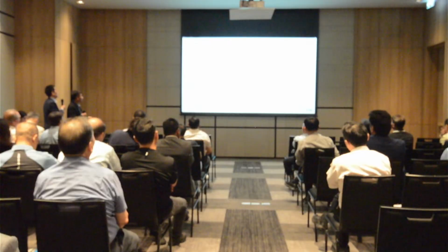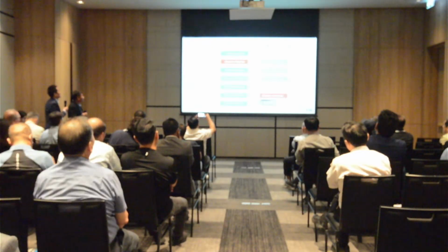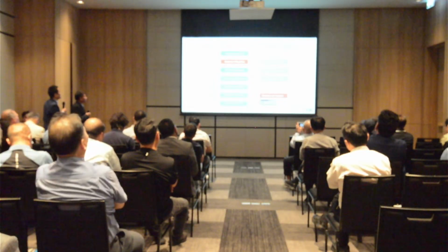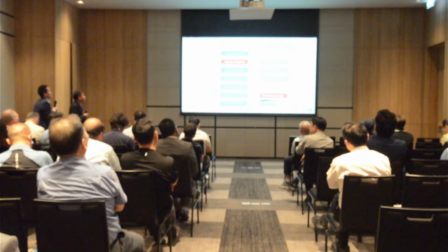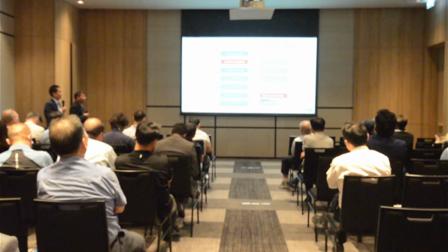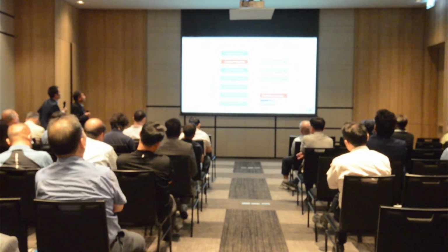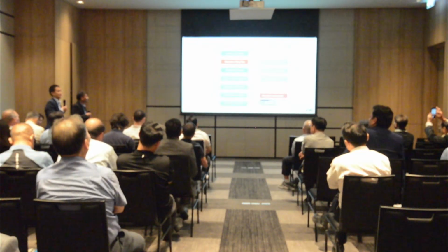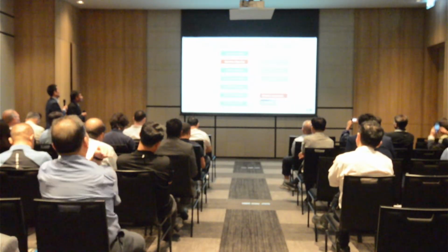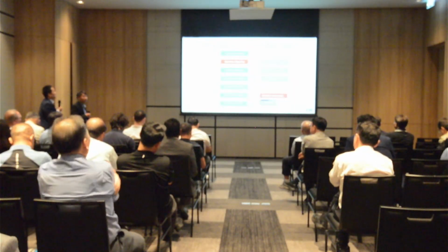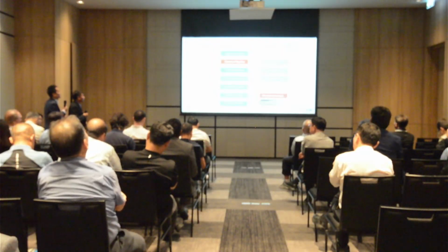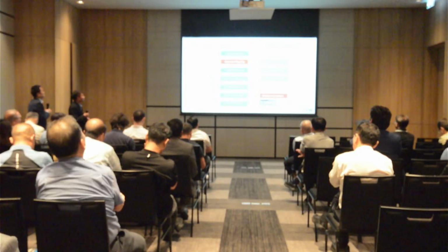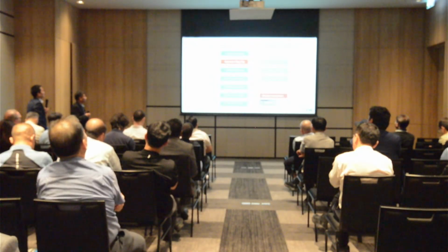Now I will introduce the process flow for the slurry mold design. First, we get the casting requirement. And then the first step is to define the filling time. And then determine the gate area.